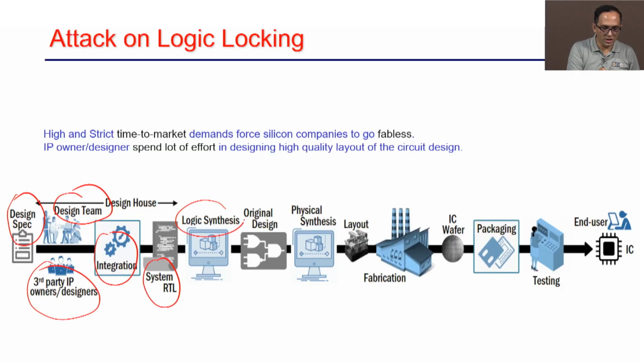You do the logic synthesis, where you convert this RTL design into a gate level design. And then you do the physical synthesis to get the layout, right. So, I will just give you a little bit of an idea here. Logic synthesis converts, you can think about your RTL design, you have some A plus B, but in the gate level design there is an adder, you will get a gate level implementation of the adder and many other things. You do the technology mapping and all.